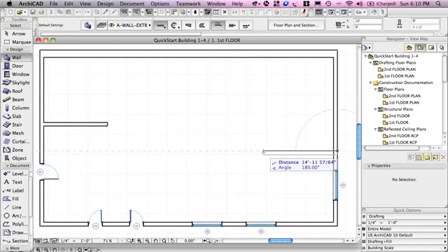Now as I'm drawing this, you'll notice that my cursor has the three-line symbol, the Mercedes, because I'm on the guideline, whereas when I'm off it becomes just a crosshair. But that cursor is attached to a rubber band line, and that is heavy, as opposed to the line below it, which shows how thick the wall is, which is lighter. So I'm controlling that line in space that we sometimes call the rubber band line, and the thickness of the wall right now is falling below.